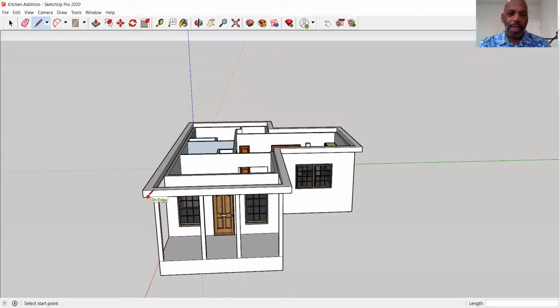All right. So now I need to establish my roof pitch. Now the roof pitch is 10 and 12. Again, meaning for every foot that I travel horizontally, I'm going to rise 10 inches, okay? Now, gable roof pitches are established by the span. Now, the span is half the total distance, all right? So we know that the width of this building here is 16 feet, and then we have a 1 foot overhang on each side. So that's giving us a total of 18 feet, okay?